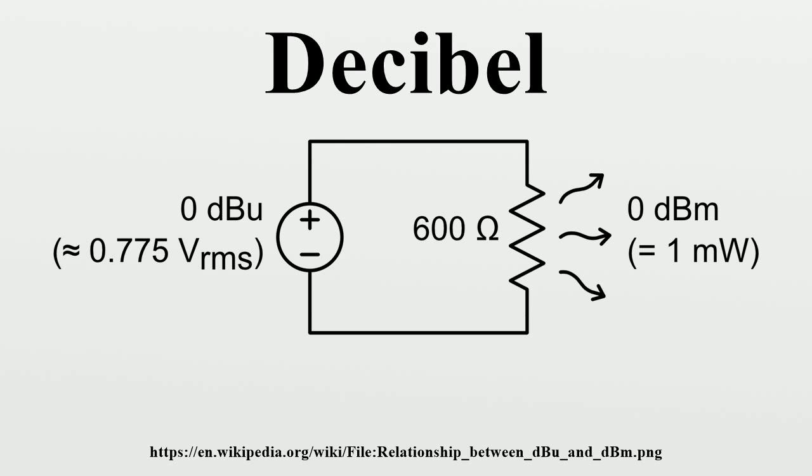Level values in decibels can be added instead of multiplying the underlying power values, which means that the overall gain of a multi-component system, such as a series of amplifier stages, can be calculated by summing the gains in decibels of the individual components, rather than multiplying the amplification factors. That is, log(A×B×C) equals log A plus log B plus log C. Practically, this means that, armed only with the knowledge that 1 decibel is approximately 26% power gain, 3 decibels is approximately 2 times power gain.